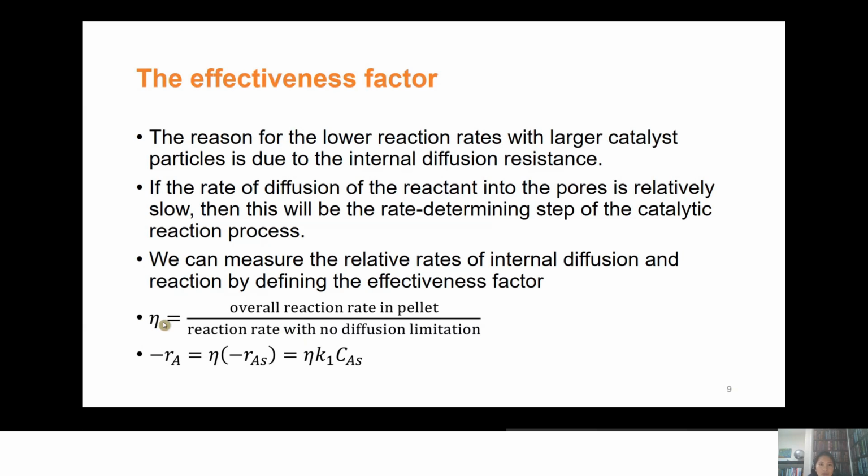Okay, so if you know the value of the effectiveness factor, eta, then you can just consider the reaction rate at the surface concentration using the methods that you have learned before on how to write reaction rate expressions. So you can write this RAS, but remember that this is at the surface of the catalyst. Same method as how you would write a rate expression before. And then you can just multiply that by the effectiveness factor eta. Eta, the effectiveness factor, will handle the effects due to internal diffusion and reaction. The internal diffusion effects are in here, as well as the surface reaction effects.